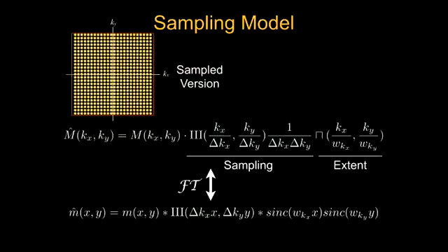Because whenever you have a convolution with the comb function, that's going to be replication of that object. So if you have an apple and you convolve it with the comb function, that means you have multiple apples, correct? If the distance is not far enough, then the apples will overlap each other.